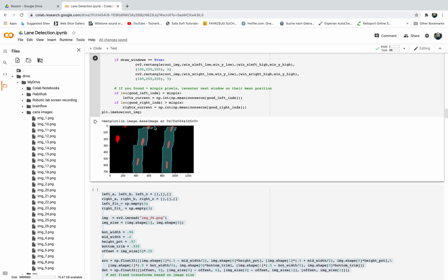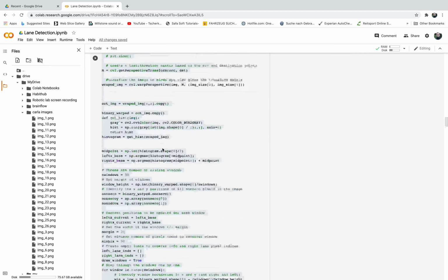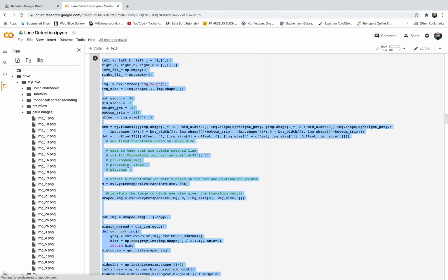And of course, if I know the polynomial model, I can get the curvature of that curve, and by getting the curvature, I can give this information to the controller to turn left or to turn right. I can also use it to predict the path and do the path planning, because if I know the curvature, I can complete this curve and predict the path of the car in order to, for example, react faster, or to have a pre-reaction to the route. And this is what you will see happening down here.